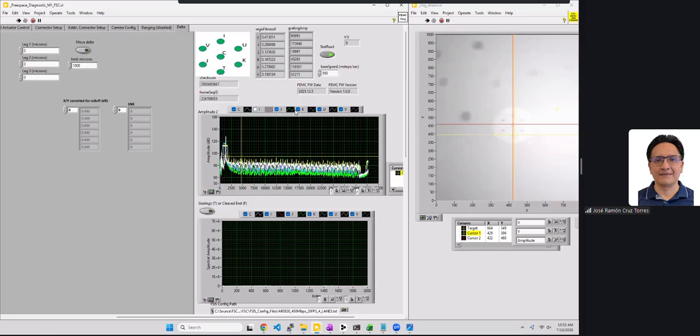I will point out, as you're aligning, you can also tell where your center core is being coupled. Because of our fiber assembly geometry, and also the gratings that we put on the center core instead of the outer cores, they look very different. This is an outer core, and this is the center core. The spread between max and min is a lot smaller for the center core, so you can use that as another piece of information.